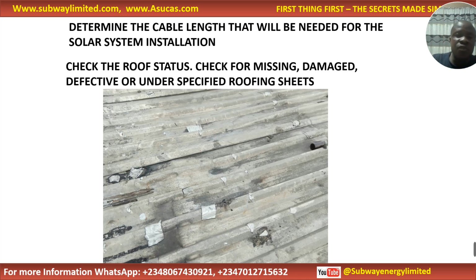So check the roof status. Don't try this. You go and see this kind of roof, call for roof overhaul, call for change of roof. So check for roof status. Check for missing roof, damaged, defective, or under-specified roofing sheet. The gauge is too small. You can't install power on it, except you want to stain your name.